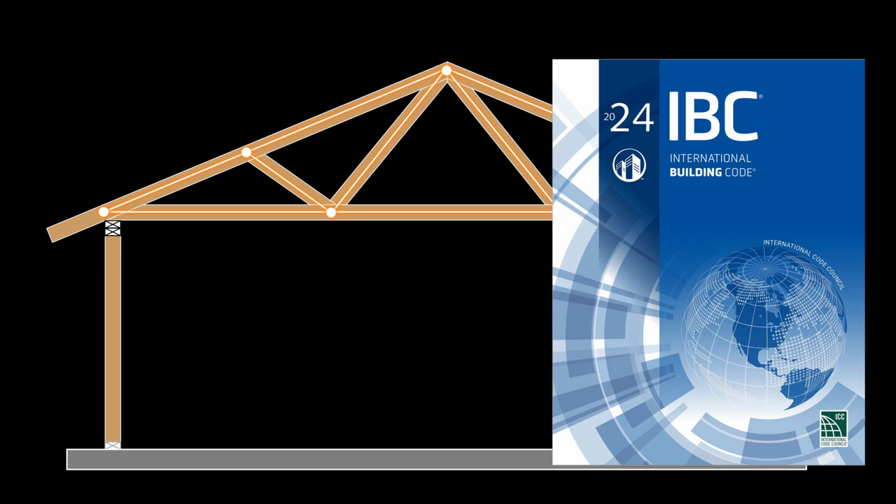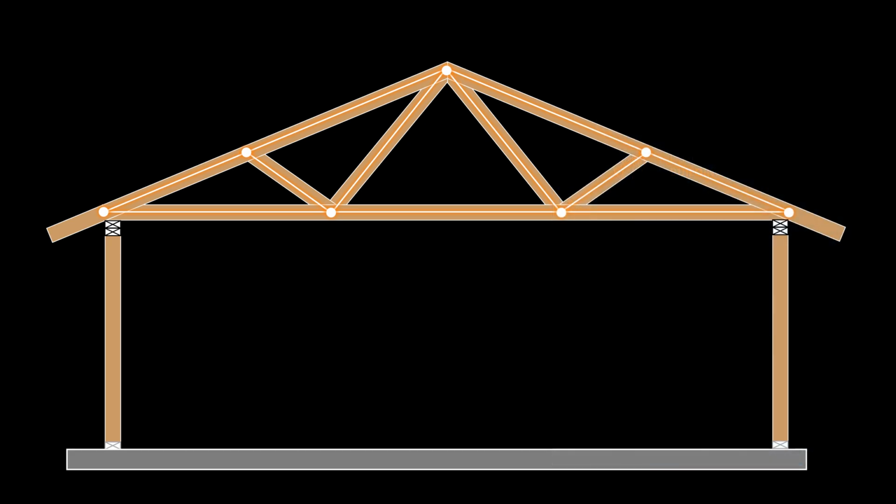For this project, we will use the 2024 version of the IBC code. The loading requirements for buildings are provided in Chapter 16 of the IBC. For this analysis, we will consider the dead plus roof live load combination.